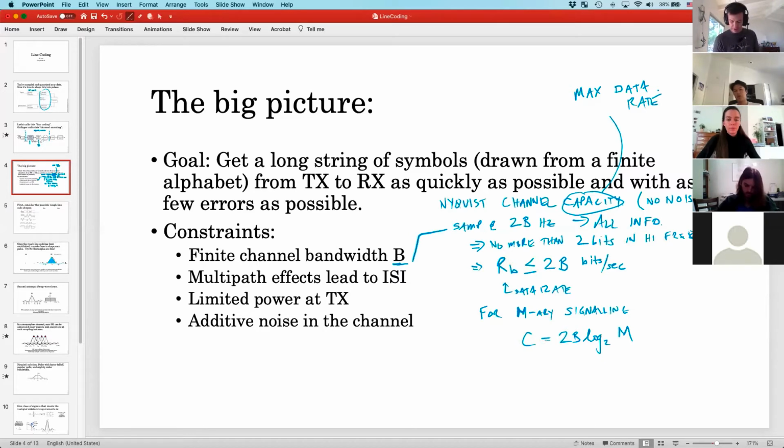You could also see this in the converse statement. Data rate is bounded by bandwidth, but if you flip that around, for a given data rate you get your required bandwidth. This is one and the same with saying your bandwidth must be at least 1/2 times your sampling rate, or your bit rate.